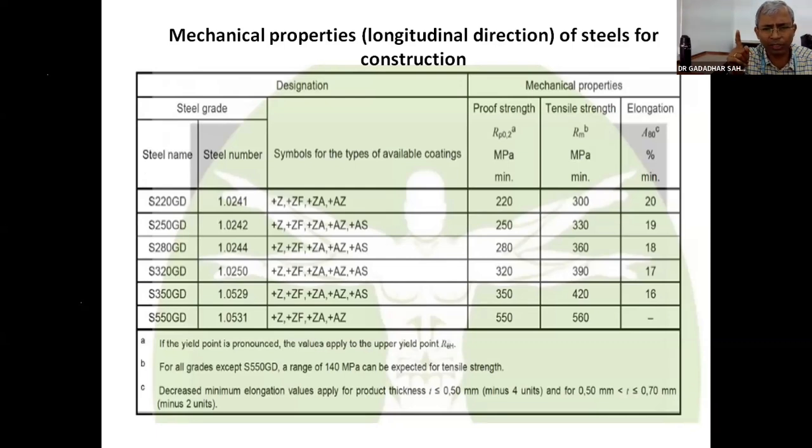Thickness is higher and strength also higher. You are saying strength 350 and thickness also higher, 3 mm. In that case, if it is thinner, there is no issue. But if it is thicker, then we have the tension leveler for straightening and flatness. To achieve the required flatness, any unevenness remaining after the HDGL hot dip process will pass through the tension leveler.